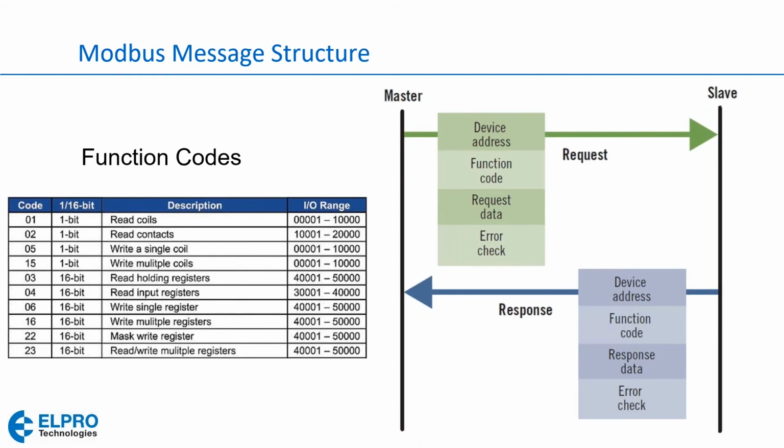By the way, when I say standardized, I would say they're about 95% standardized across Modbus devices. Some manufacturers have put in additional features that might not exactly conform to the Modbus standard, but with our ELPRO products, we don't necessarily support all of these function codes. We just support the most important ones that are required to be able to read digital inputs and outputs, and analog inputs and outputs. Okay, so just a bit of an explanation on the Modbus messaging format.